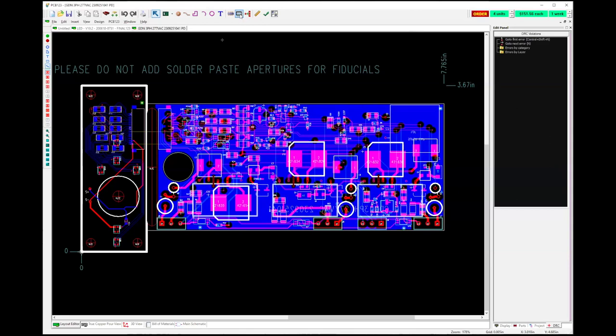So you'll need to use the schematic function, place an actual component with the part number and all that information attached to it. And a lot of times you'd be surprised, the parts that you're looking for will already be in Snap EDA's library or selection. You can just go search for it and place it that way.